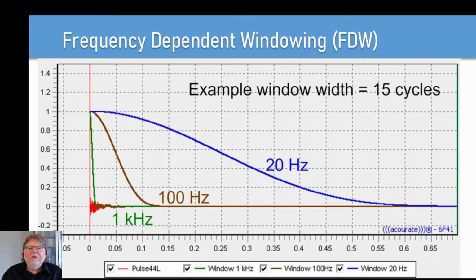While this example uses 15 cycles as a single frequency-dependent window setting, the DSP software we use can adjust both the high and low frequency time windows independently. This allows us to calculate the optimum frequency-dependent window sizes based on your room size and statistical analysis of modal distribution and early reflections density. This analysis gives us the smoothest integration between room plus loudspeaker below your room's transition frequency and the loudspeaker's direct sound above your room's transition frequency, or diffusion zone, as we discussed earlier.